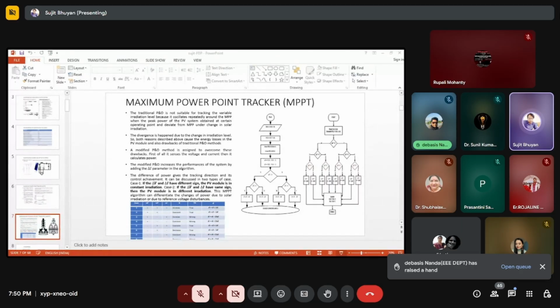The basic work of pulse width modulation is to give the pulses. Previously I described the gate triggering method used to trigger the switches. So this signal is given to the PWM, and the PWM gives pulses to the IGBT switch by using the gate triggering method. This is the whole criteria of the VSC controller to connect the microgrid to the grid, stabilizing the variable and constant frequencies and connecting it to the grid. This is not the only method; various methods are there. I will show you another one or two methods of how grid integration can be achieved.